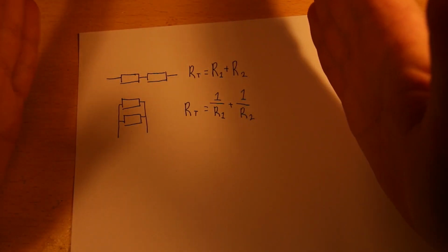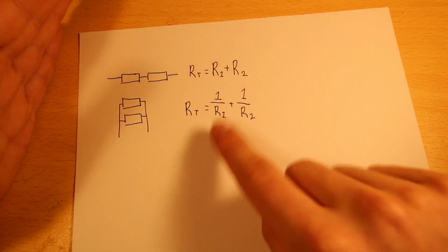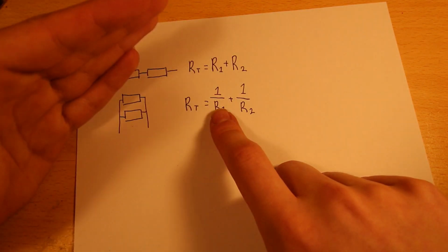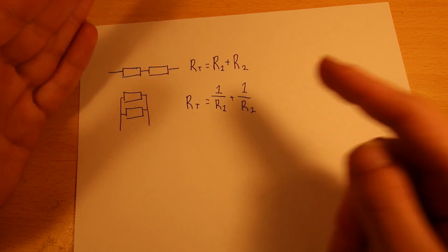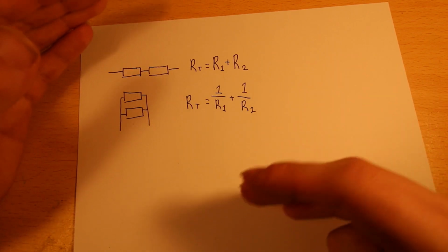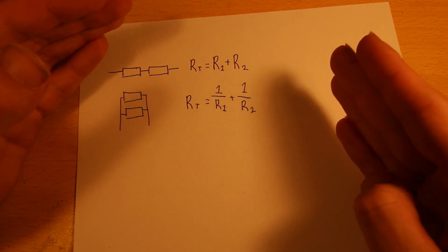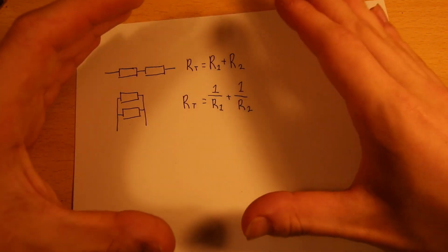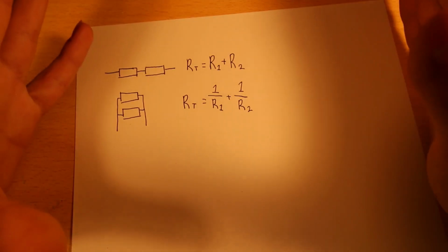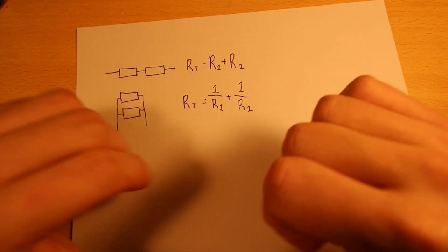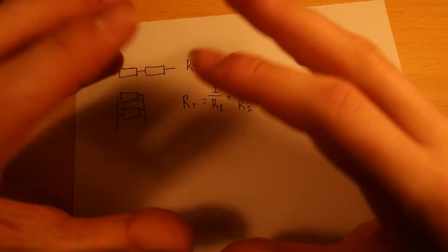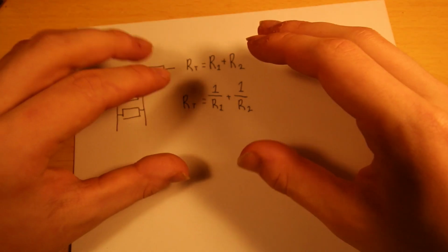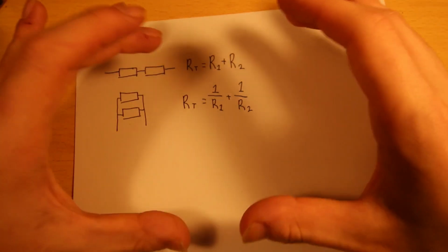So most of the time, if you had to say R1 is the cable resistance of 0.5 ohms, and R2 is the insulation resistance of, say, 20,000 million ohms, the R2 is so huge in comparison to R1 that people just say we can ignore it. And that's fine, you can ignore it because it is a negligible impact it will have, but it is there.